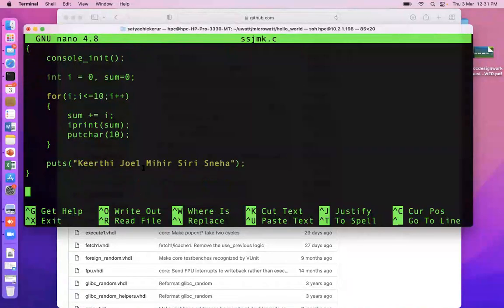We have just used putc. Printf is not possible here yet, because we have to put it as a string, character by character. So printf is not working, scanf is not working. Very small minimal things we have to modify.